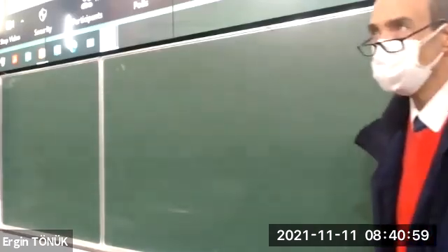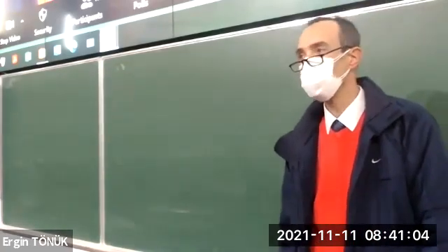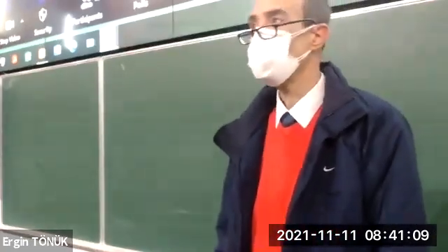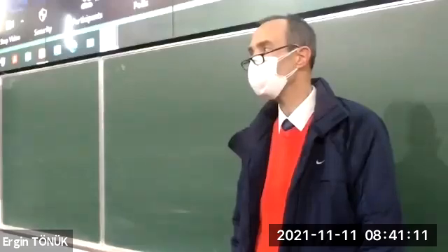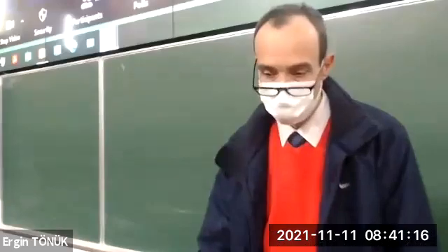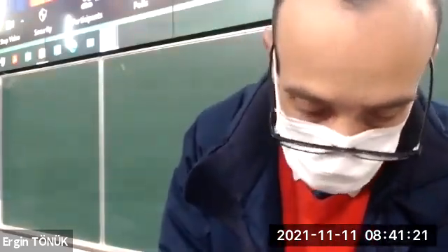Last time we discussed two positions of a moving plane. We have seen Chasles' theorem, which said the motion between two positions of a plane can most simply be obtained by a rotation about the pole. So we have seen how to determine the pole of the motion for two positions, graphically and analytically. And actually today I will just add one alternative method in determining the pole.